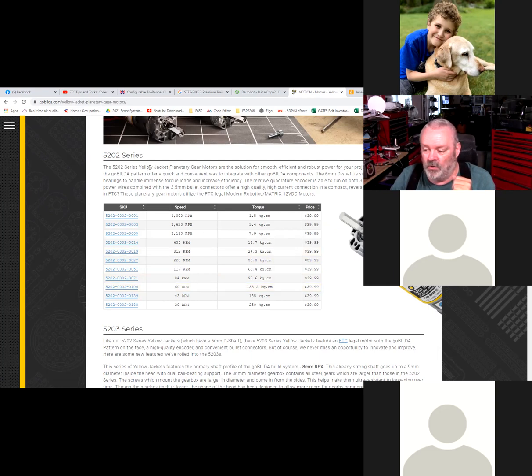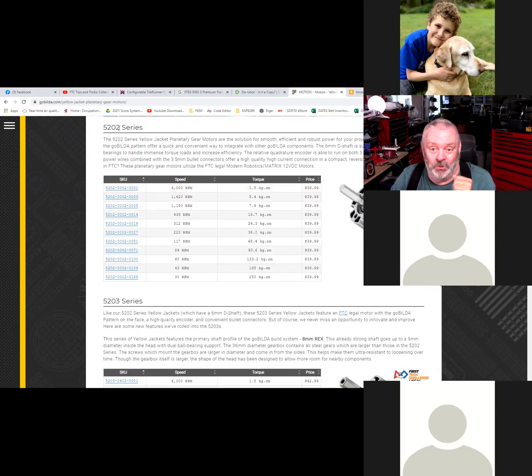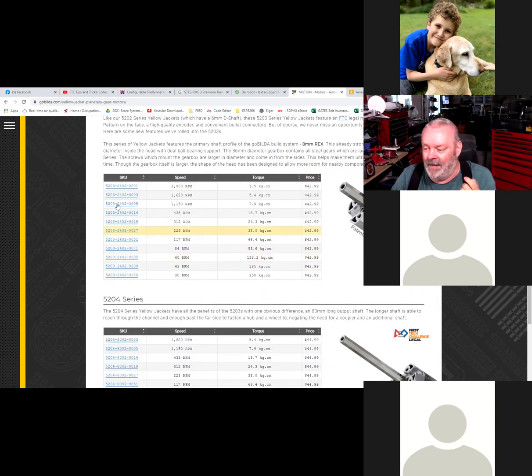So if I look on here, they have the 5202s. I don't know which one you've got. You got the 03s? Yeah. So they have a hex shaft? Yep. Oh, good. All right. So you can get different gear ratios. The way their part numbering system works is that there's the base, and the last 4 digits tell you the gear ratio of the motors. So you have 19-to-1s, which comes with a default kit.